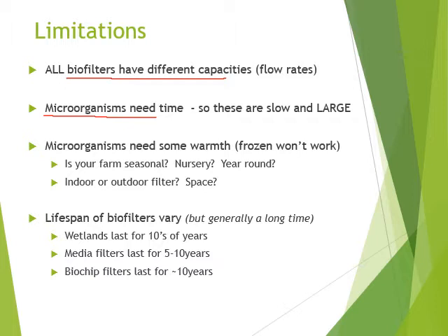So that also indicates the size of the unit. So if you have a low bacterial load in your water, you can get away with a smaller biofilter. If you have a higher bacterial load, you need a bigger biofilter. These things get complicated and they're beyond the scope of what we're trying to cover in this lesson. But you should be aware that you have to match the filter to your biological load.